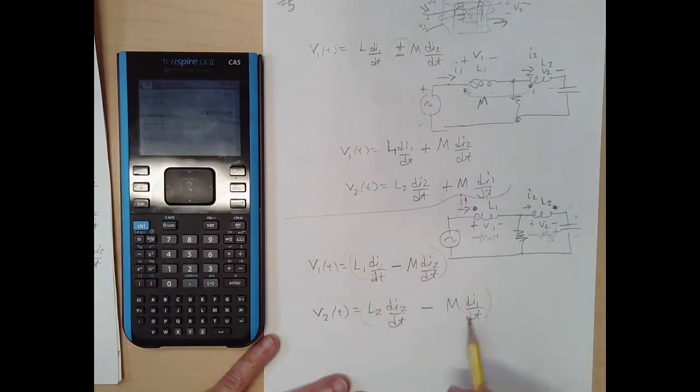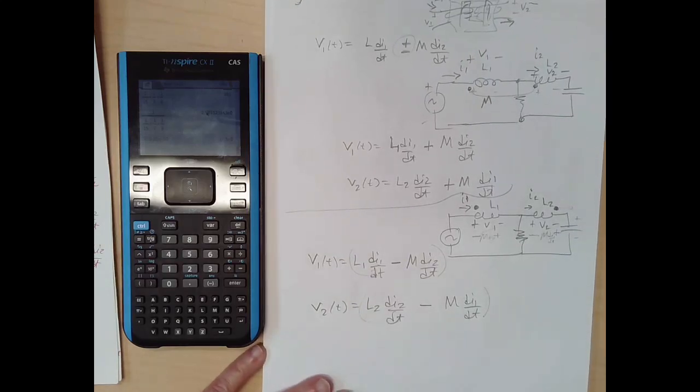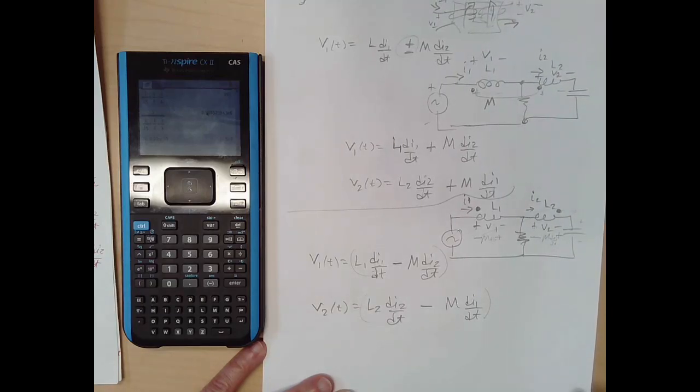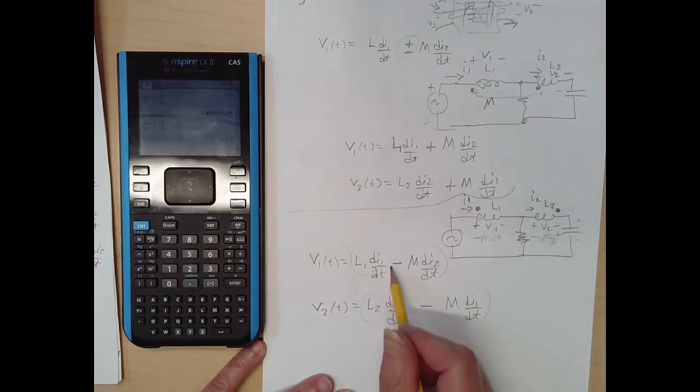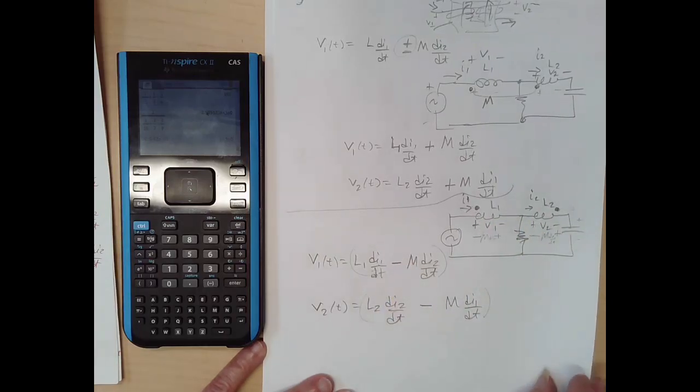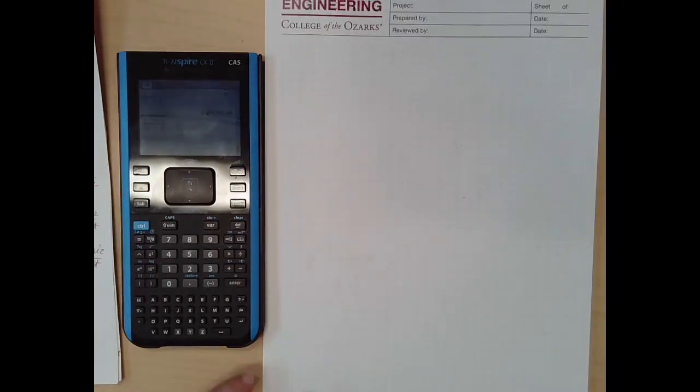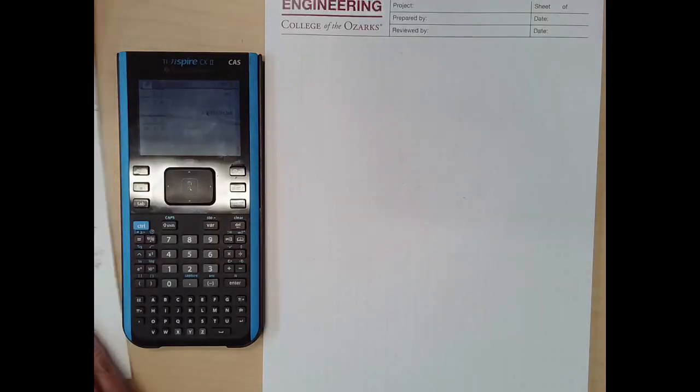And we can also do mutual inductance in the frequency domain, which is where it makes the most sense, where we have phasors and so forth. Then we wouldn't have dI/dt's, we would just have j omega L and j omega M, right? And the I's and V's would be phasors. But mostly we just want you to understand the dot convention, how that affects the mutual, whether it's plus or minus. Okay, let's look at another kind of problem here.